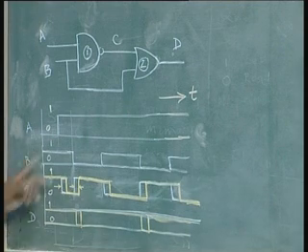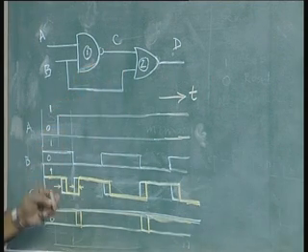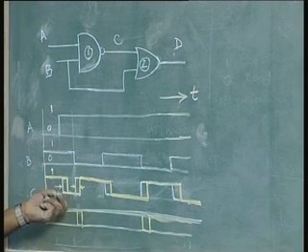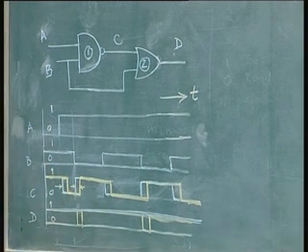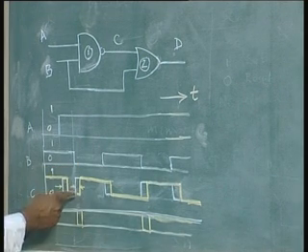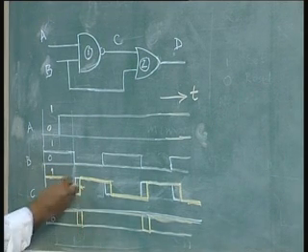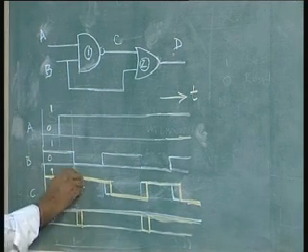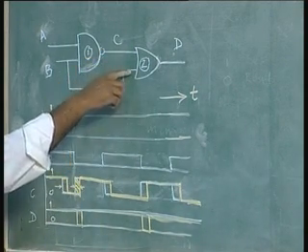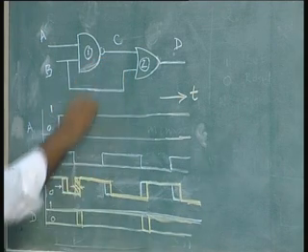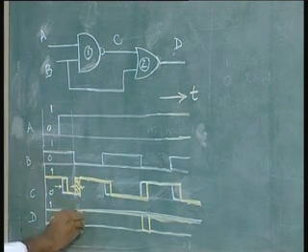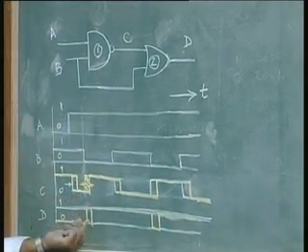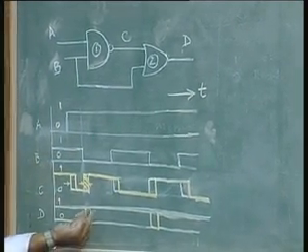Now, making these OR gate inputs as this and this, the new yellow line, there will be short durations during which there will be both zeros. For example, this duration here is the duration for which B is 0 and C is 0. B and C are both 0 here, so the output has to be 0. Originally we said D was 1 continuously. Now I am saying because of the propagation delay, this is 0. Again this 0 will not occur here, it will occur a little shifted.